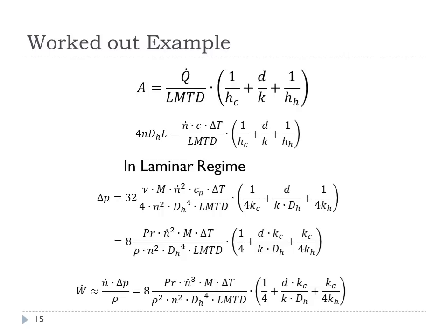So this is one thing I want to point out here. The amount of work needed to make up for the delta P, basically the frictional loss of work, goes inversely with the log mean temperature difference. So you'd think, well, let's have a large log mean temperature difference. But of course, the exergy destruction in the heat exchanger due to heat transfer is going to be roughly linear with the log mean temperature difference.